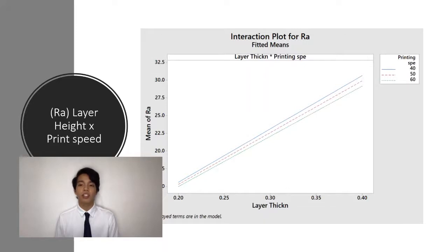The researchers observed that the thinner the layers, the longer it took to complete the print. This is mainly due to the additional layers to be printed, and the rate at which the filament can be extruded to the tip was lower. As a rule of thumb, the print time tends to double as the tip moves from one tip size to another.